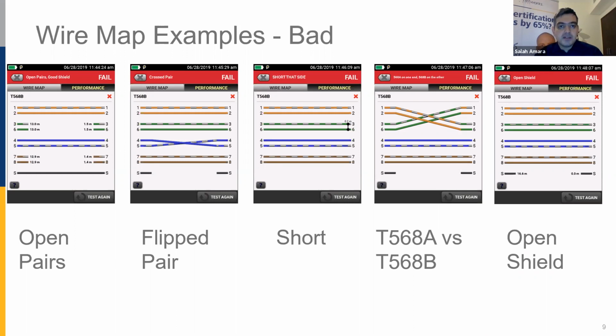But there are similarities. Some parameters are needed, like what I explained, like the length is not specified in ISO while it's specified in TIA. But in ISO we have a propagation delay, which will lead to the same result. So there are differences, but there are also big similarities or equivalents. So when we are testing Cat6, there is an equivalent to that in the ISO.